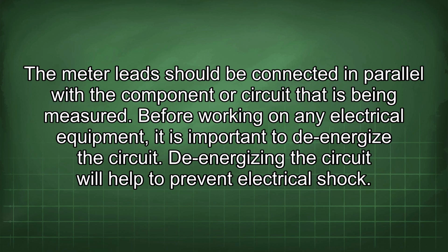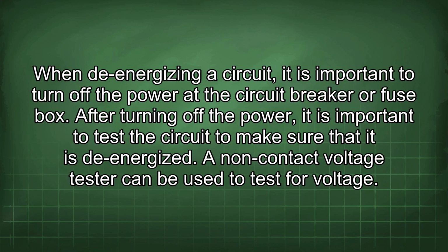Before working on any electrical equipment, it is important to de-energize the circuit. De-energizing the circuit will help to prevent electrical shock. When de-energizing a circuit, it is important to turn off the power at the circuit breaker or fuse box. After turning off the power, it is important to test the circuit to make sure that it is de-energized. A non-contact voltage tester can be used to test for voltage.